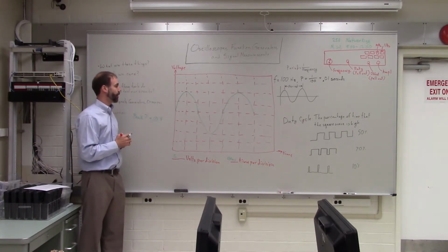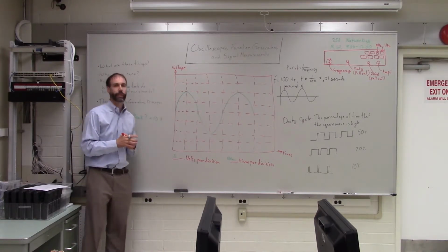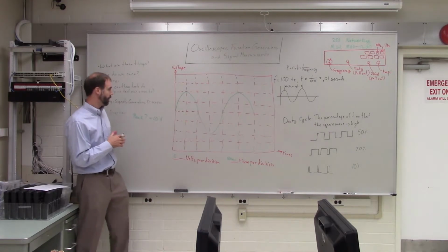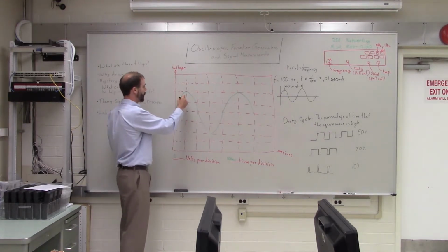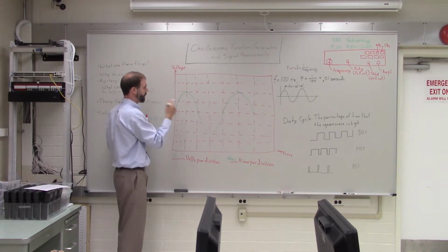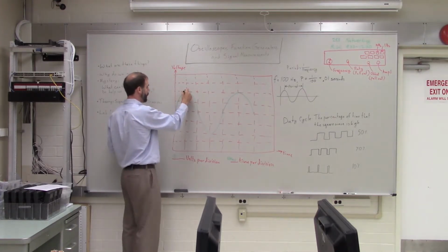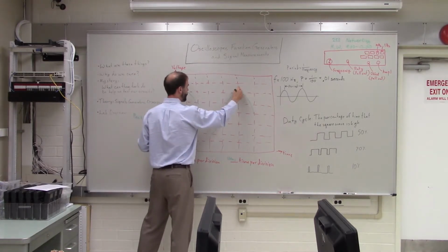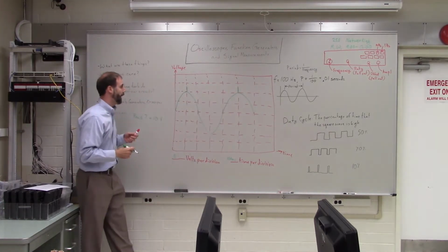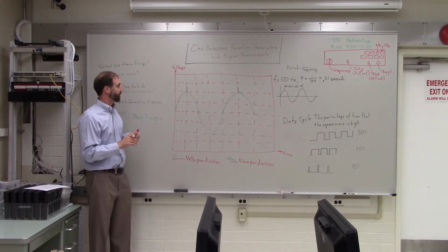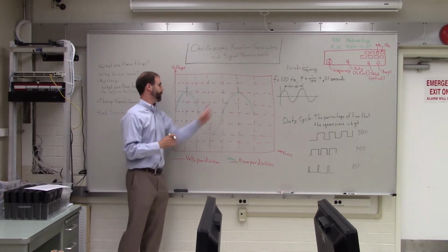What about the period? Can we estimate the period here? Yes. Yeah. What would the period be? 400 milliseconds. Yeah, exactly. So remember, the period is the time from one spot on a wave to the same spot on the next wave. So we could look from here to there, for instance, and then we could count how many divisions there are in between those 2 positions.